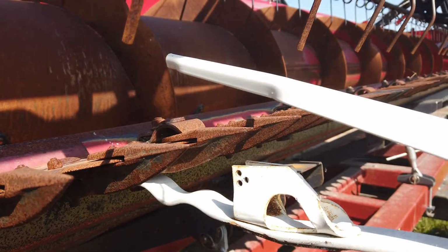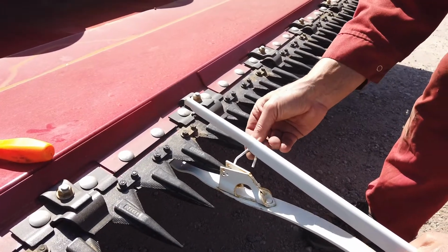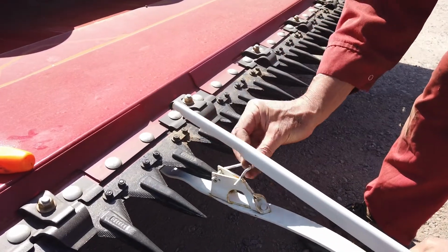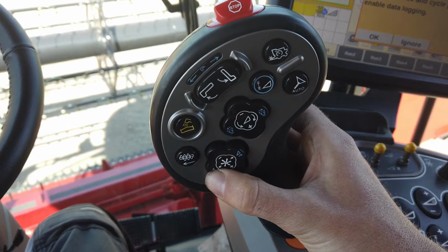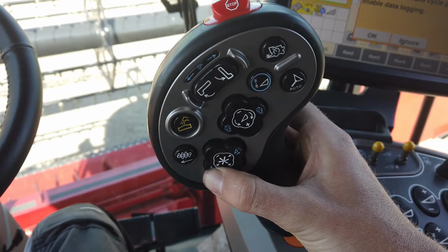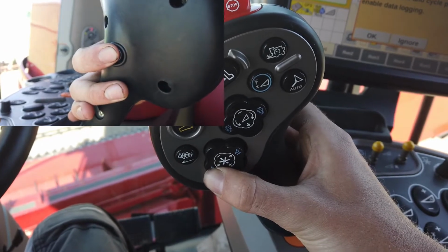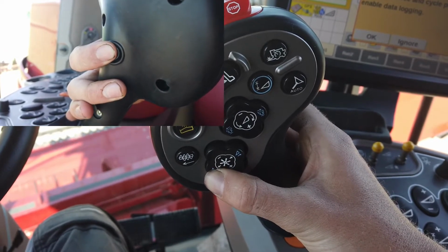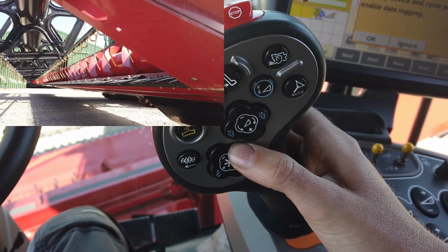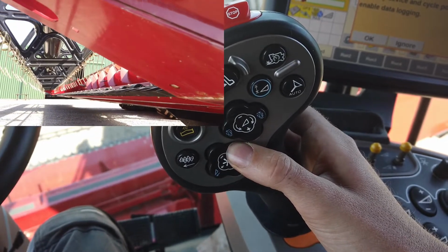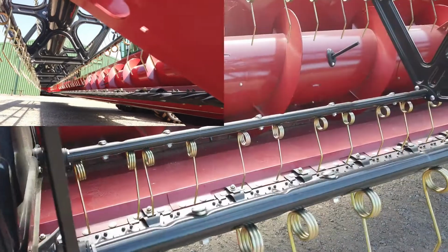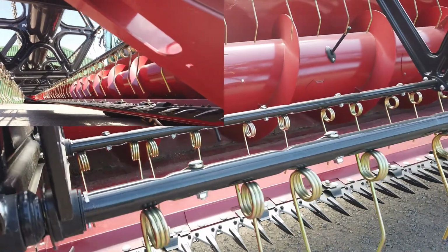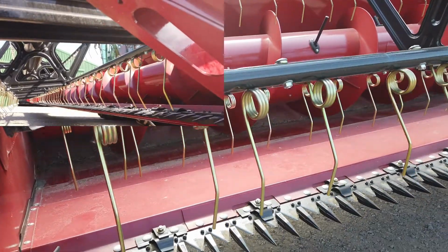Remember though, for crop lifters to work correctly, the knife must be about 4 to 5 inches away from the ground. The knife can be pushed in and out on the move by using the reel fore and aft button in conjunction with the shift button on the back of the multifunction handle. Push out completely for oilseed rape and right in for very short crops, and adjust as necessary to suit the height of the crop to get easy feed of cut material into the auger.